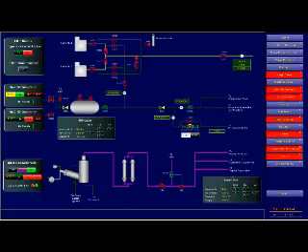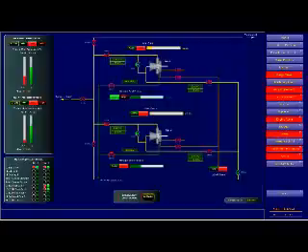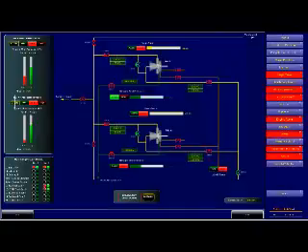So let's see the tank pressure. 15.4 kPa, very good. It is not so high or not so low. The condition of our compressors, they are on standby. No, sorry, they are not on standby. We will put them on standby if we need to create the vapor.